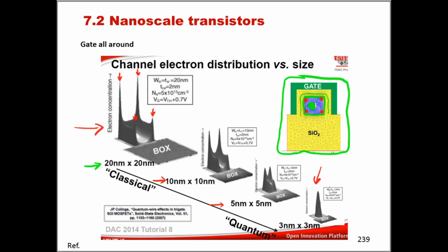So in future devices, gate-all-around devices that are in the size of really a few nanometers, the electrons travel very close to each other in the middle. This is quite a remarkable result. In the quantum situation, the electrons like to stick together and travel in the middle of the silicon nanowire. So this is quite a nice result that I wanted to point out to you.